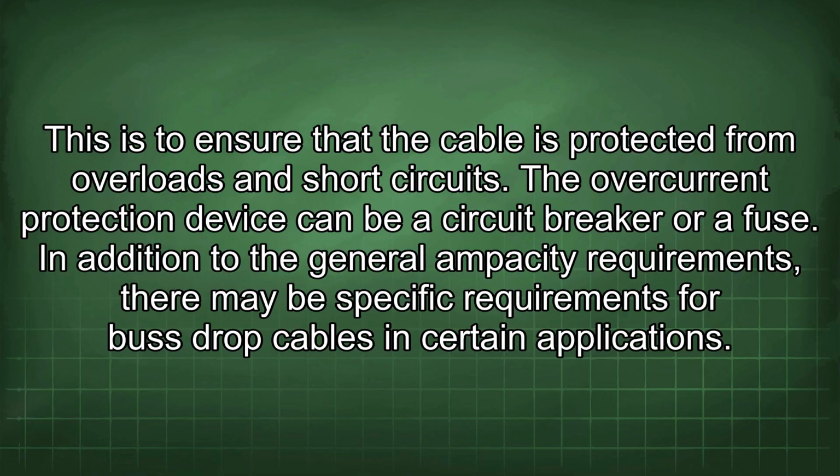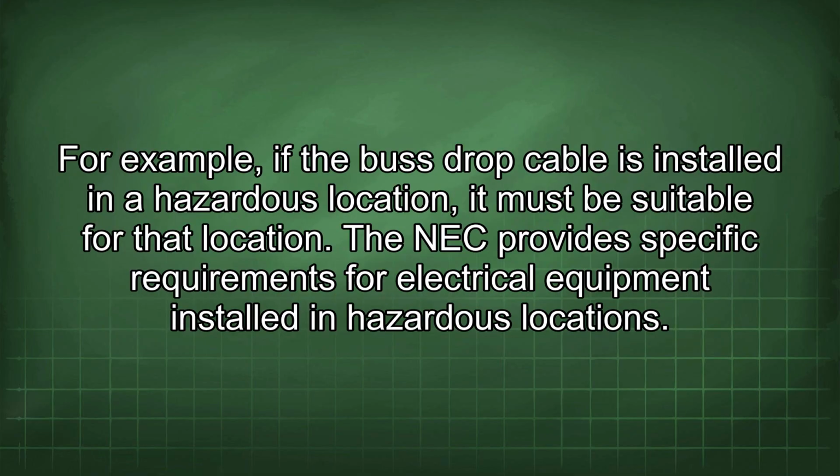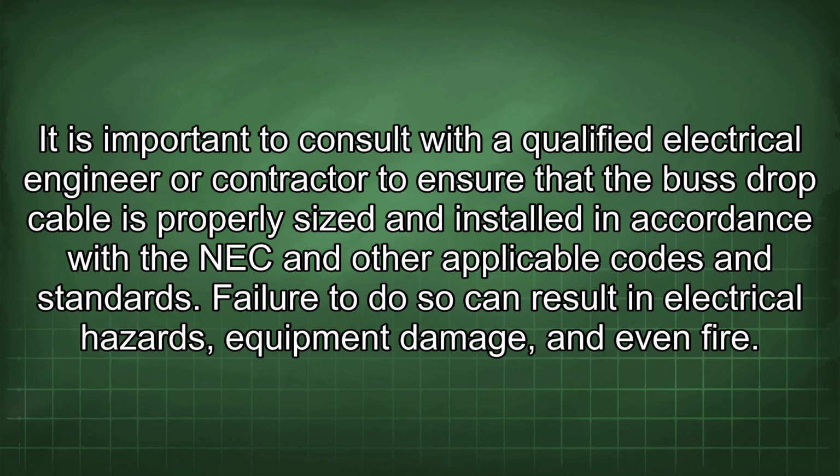In addition to the general ampacity requirements, there may be specific requirements for bus drop cables in certain applications. For example, if the bus drop cable is installed in a hazardous location, it must be suitable for that location. The NEC provides specific requirements for electrical equipment installed in hazardous locations. It is important to consult with a qualified electrical engineer or contractor to ensure that the bus drop cable is properly sized and installed in accordance with the NEC and other applicable codes and standards. Failure to do so can result in electrical hazards, equipment damage, and even fire.